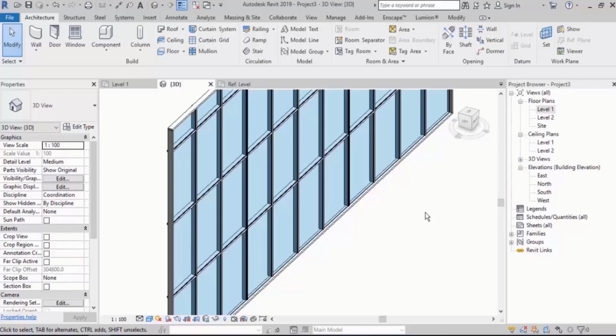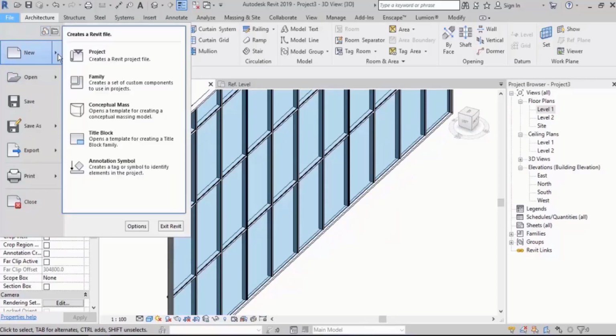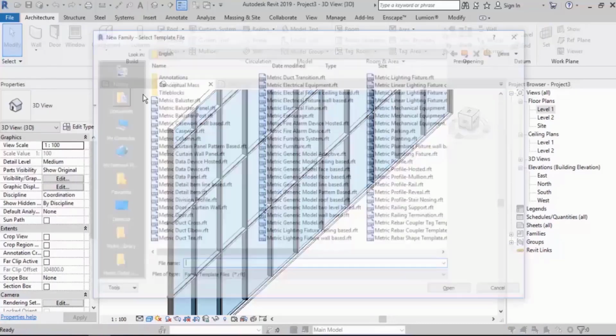Well, now I want to make a new mullion with a new profile. Well, obviously I've learned not to go and duplicate the mullion first. I need to design the profile first to have it, and then I can design a mullion with it. So at first, let's design the profile. We go up to this part. Remember to check the steps of the work to answer my question.